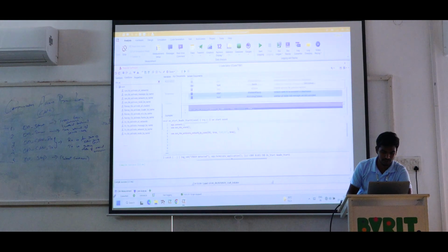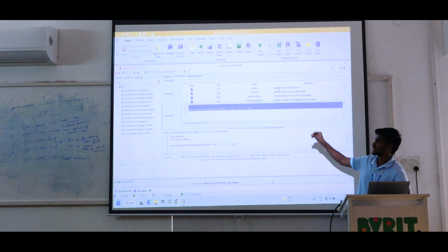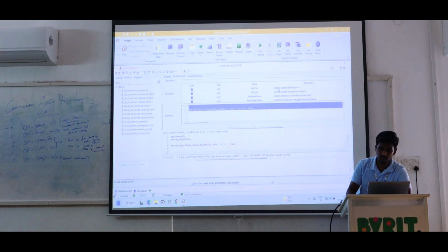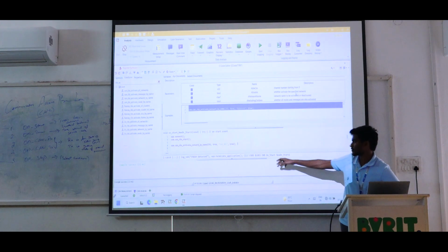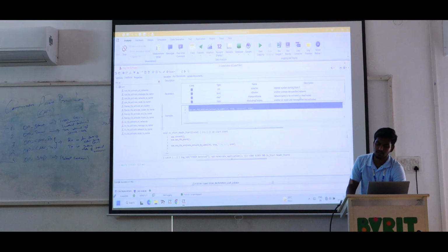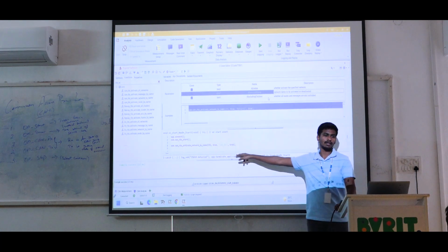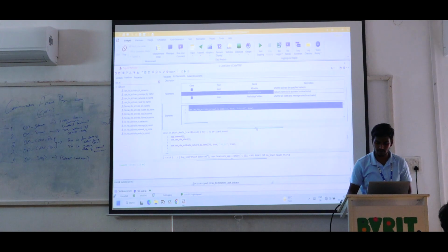Please open the function parameters in parallel. These parameters: the first one is the index channel, so the channel number starting from 0. So we have to take it as 0 or CH1, both are the same here. The second one is enable or disable, meaning whether to activate the specified network. This true is for activating the network. If you give false, it deactivates the network. The next one is the network name. The fourth one, including children, means all nodes. Whatever nodes it carries will be activated, but we don't want to activate all of them, so please give this as false.